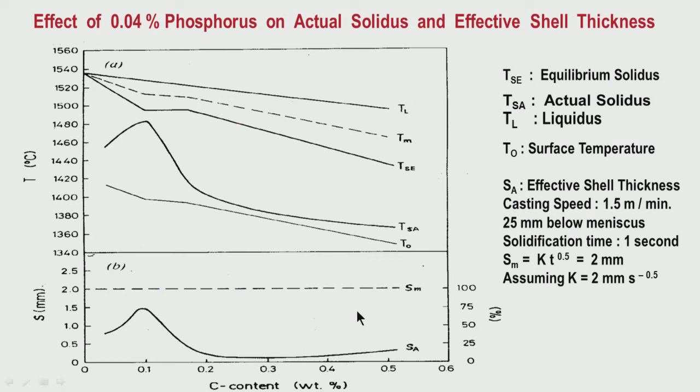Different levels of carbon basically indicate different solidification modes that I have explained in the last discussion. So, all these are related. The alloying elements control the solidification mode by controlling the carbon equivalent. In plain carbon steel, that means steels which have just carbon, the iron carbon diagram is the criterion. In low alloy steels, we have to calculate carbon equivalent. That means how alloying elements like manganese, silicon, chromium, nickel, present in small amounts, affect the carbon activity in solidification. So, that will have an impact on the carbon equivalent.